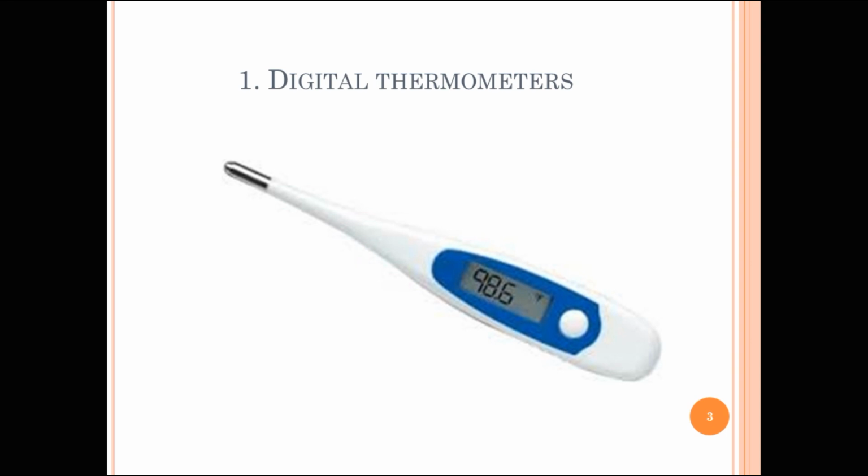If the number of measurements increases, this process of conversion will take much time and even bring chances for error. Moreover, the reference junction temperature must be calculated if it is not the ice point temperature. We have seen that linearization is needed for both thermocouples and resistance temperature detectors. The linearization method may be analog or digital. Digital linearization may be either non-microprocessor or microprocessor based, of which linearization with a microprocessor is widely used.